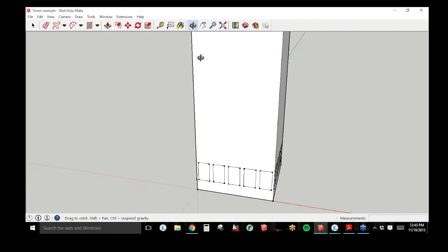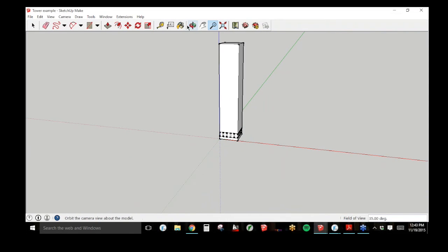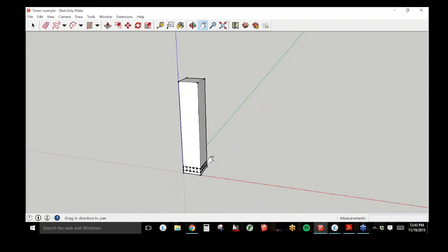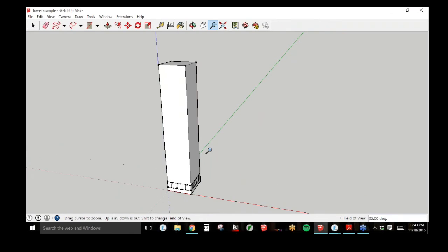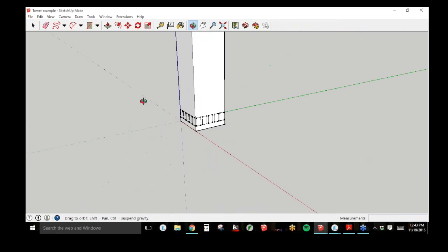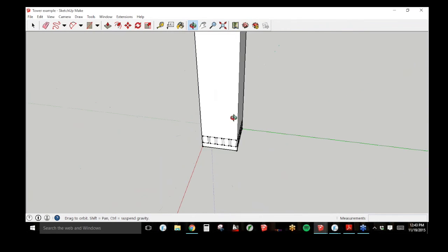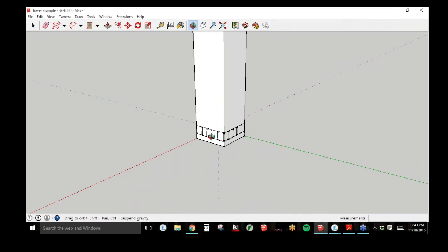Let's say we're doing this tower here. This is what it looks like. And then it has these uniform windows across it. So there's 5 windows across. Let me just have it on all sides for simplicity for this example. We would come in and create this. We just create one row of these windows. You could even create just one really, but you create the whole first floor if you'd like. You need to create at least one per wall to use this trick I'm going to show.